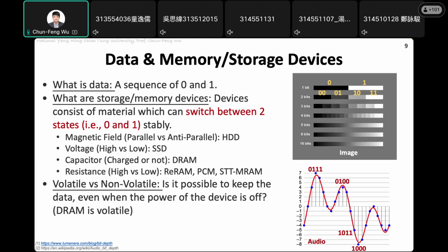So next time you reboot your system, all the data inside the DRAM and SRAM will not be stored. And the reason that after the next reboot, most of the data you stored in the DRAM is still there, is that your computer will store most of the data from memory to the storage device before the power is really off. So the next time you reboot, the data can be fetched from the storage device, and it pretends like the data is in the DRAM.